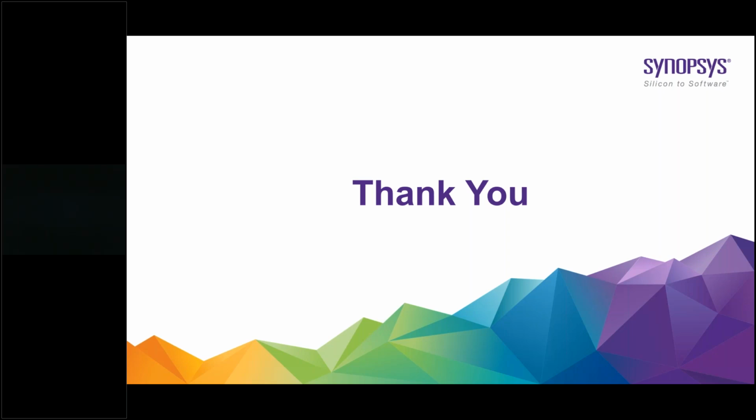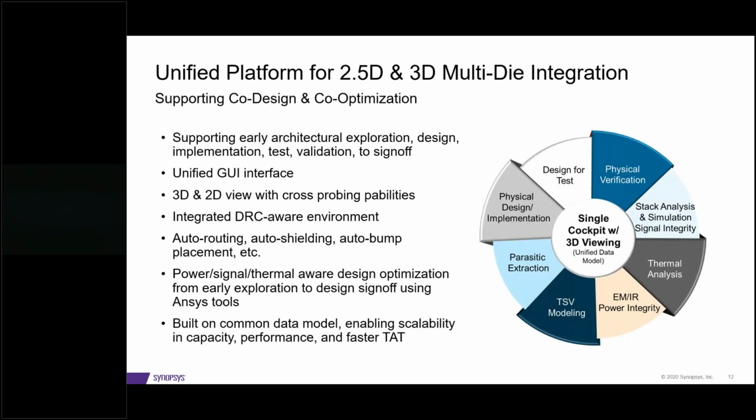Rita, quick question. The last slide you presented, does Synopsys have such a tool today? Yes, we have the 3D-IC Compiler that was announced earlier this year in April. Yes, we have a single cockpit environment that does anywhere from exploration to design sign-off. And it has all the capability of SI, PI, thermal analysis, and of course, design and implementation of both fan-out and silicon interposer. This is completely vendor agnostic.